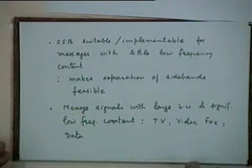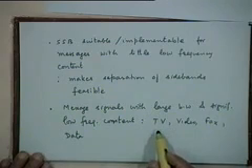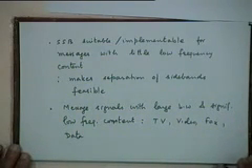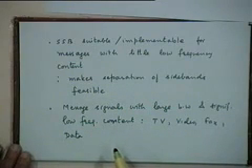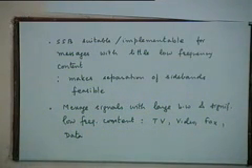All these kinds of signals have significant low frequency content. So this separation becomes more difficult, and if you try to enforce it, it will create all kinds of distortions which are not acceptable. Okay? And it is for such applications that one thinks of VSB.